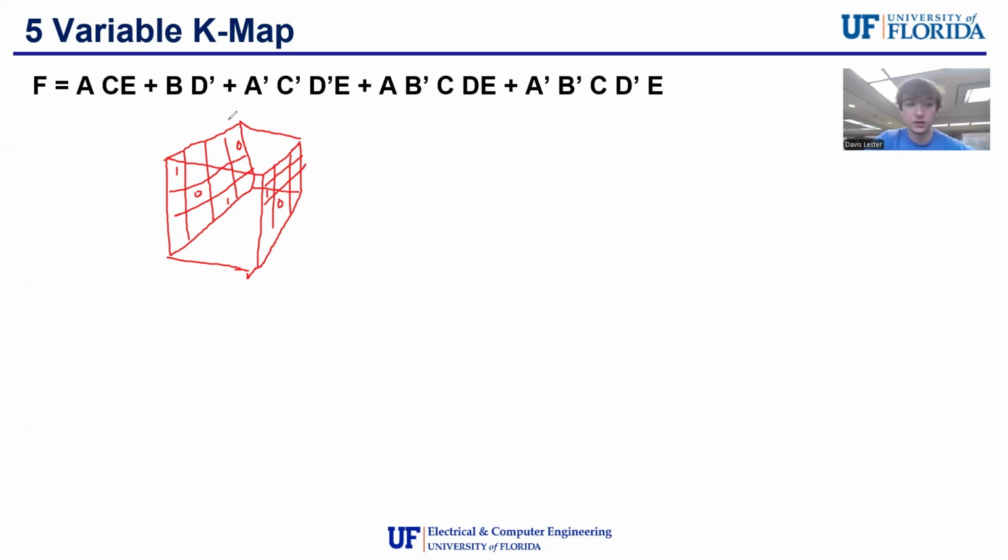But how this works is in this bottom K-map here, we'll choose one of the outputs. I'll say E. So we'll have E true, E equals 1. And the top K-map will have E equals 0. You can choose any of these. In fact, it's probably more advantageous for you to use A, which is your most significant.